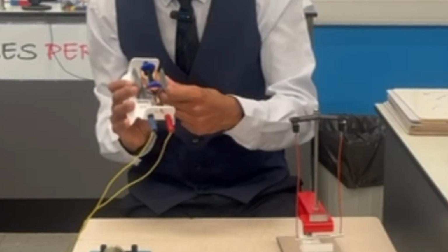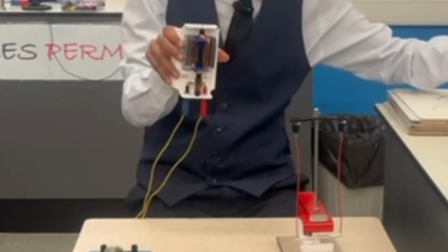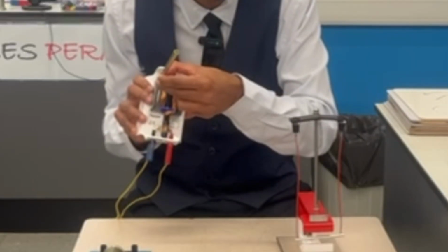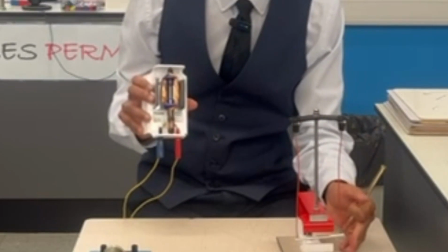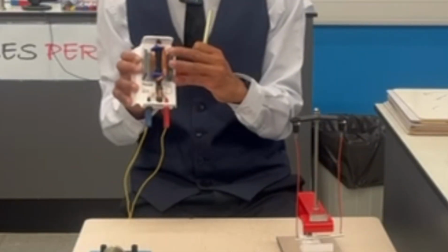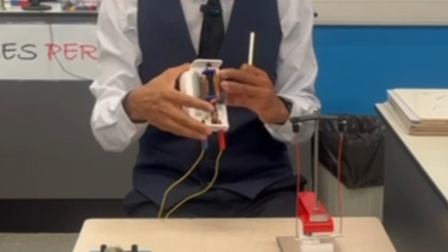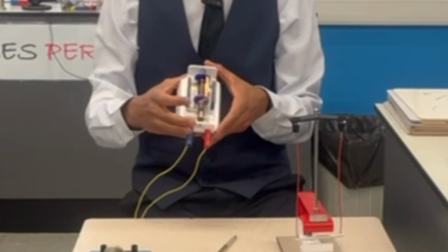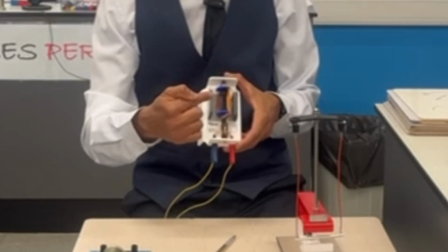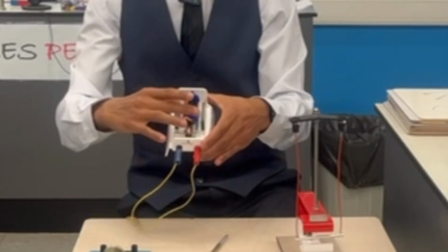And then just on the side here, can you see the two magnets? These two magnets, and the wire is this wire. Once we send electricity through it, guess what's going to happen? The two fields are going to interact, giving you a force given by F = BIL. However, one is going up, one is going down. So what are we going to have? What we call a couple, a turning force, one way with the other one the other way. So this will spin.